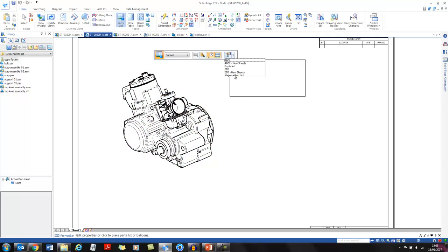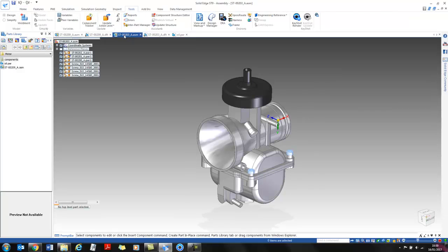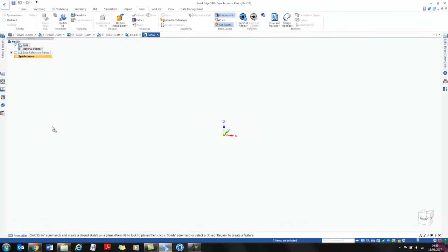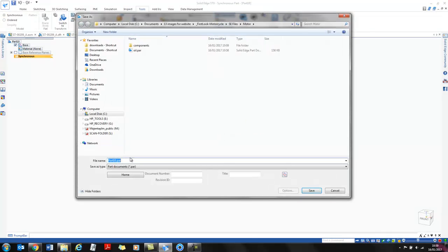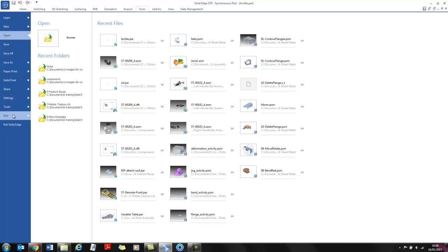On your drawing, you will see that the non-graphical part has been added to the bill of materials. It has a quantity that's defined from the occurrence properties. We will now look at creating a non-graphical part that has no units. For example, you may require a small quantity of Loctite on the parts list, documented with a quantity of as required. I will now create a new part for Loctite.